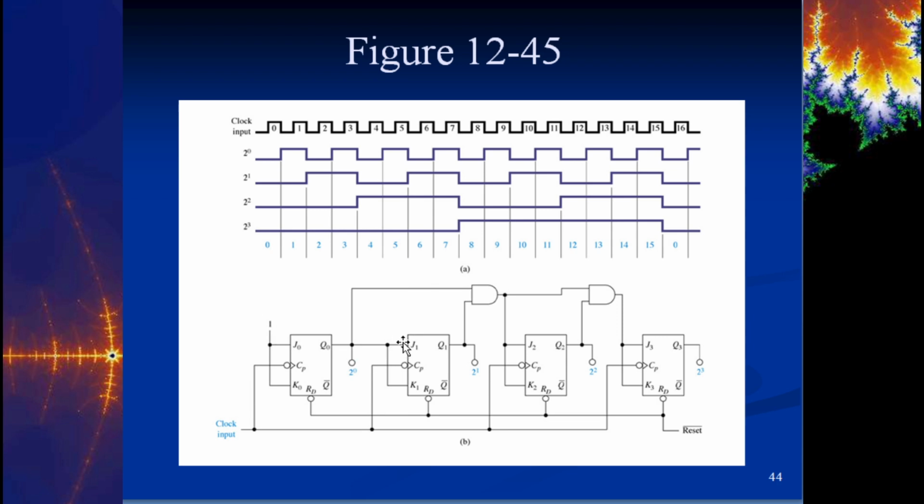The next JK are based on Q. Okay? And then the next JK is the AND of this Q and this Q. Right? And now this right here will continue on. No matter how many flip-flops you have cascaded together here, you will have this AND gate structure at the top where you're taking the present Q and ANDing it with the previous Q. Or in this case, it's the previous AND gate. Okay? That becomes this top leg the whole way across. If we had 5 of these, we would take this output and this Q and AND them together, and that would become the JK for the next flip-flop.